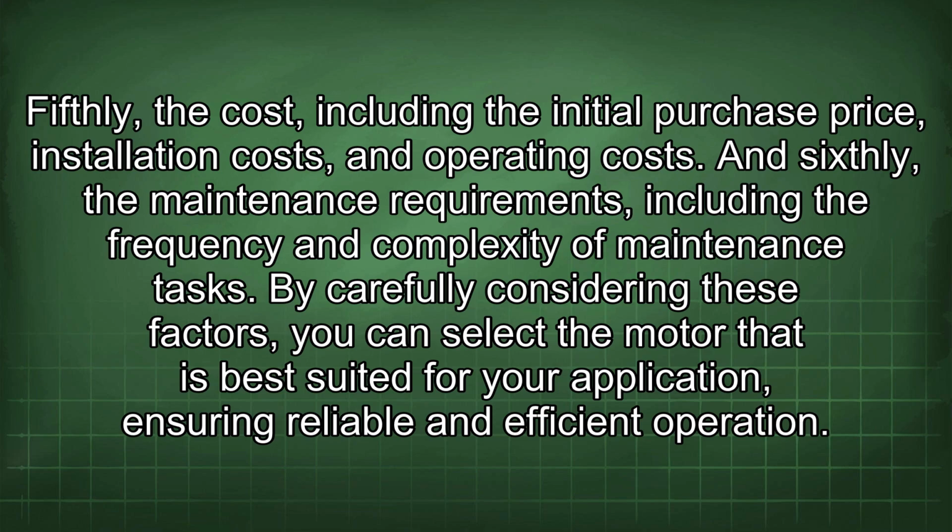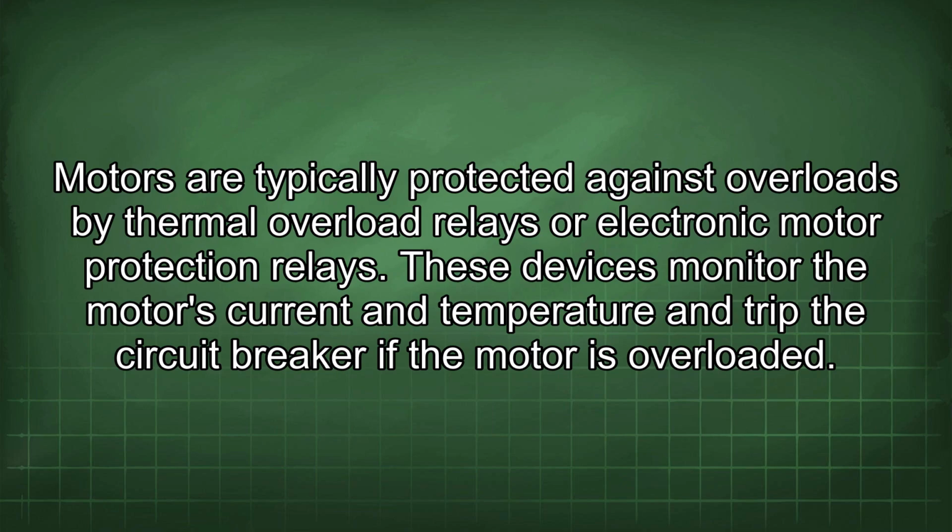By carefully considering these factors, you can select the motor that is best suited for your application, ensuring reliable and efficient operation. Motors are typically protected against overloads by thermal overload relays or electronic motor protection relays.